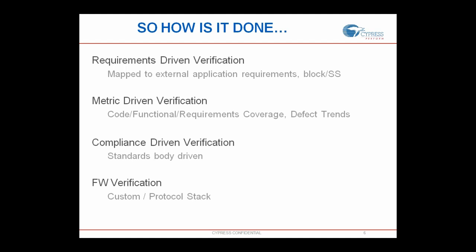Then the most important these days, with so many newer protocols going into one single chip, is compliance-driven verification. You may have a lot of test cases, you may have a wonderful coverage model, everything is met, but then the silicon has a bug in compliance. The reason? Because these days all the protocols have to be certified by a third-party test facility. For example, for USB compliance, tests are to be run in a standard facility.